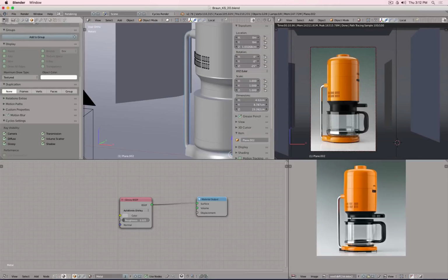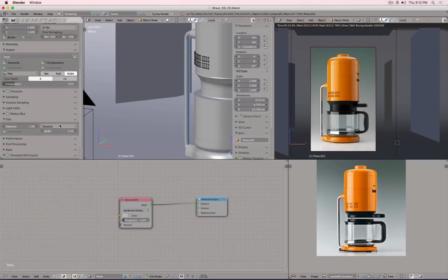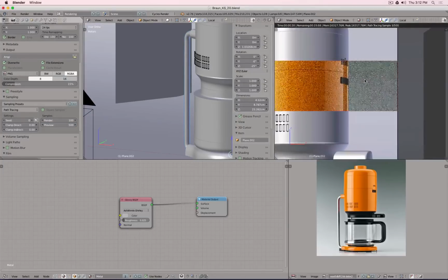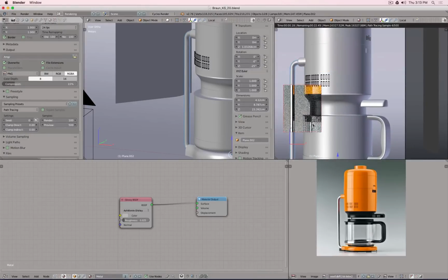So to render this one out, I have my size set for how many pixels I need. I know, let's see, maybe how many samples I need for the rendering. 100 is not clean, so maybe I set this to 500, and maybe I make a quick render border for this area and let it render, and then I observe at one point, does everything look clean? So looks like maybe 300 samples. Okay, what about here?